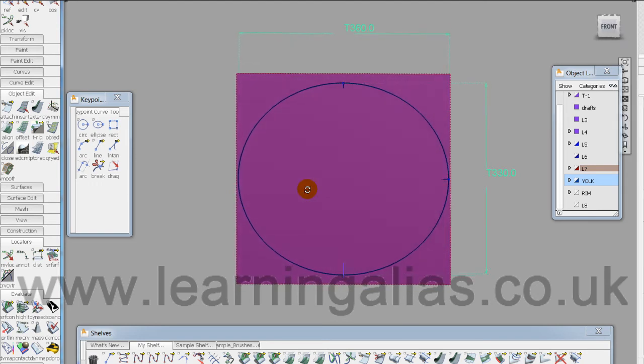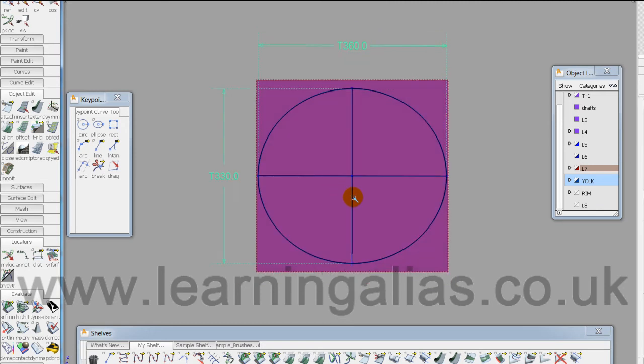It's okay for concept work, but if you want something better, you're going to have to find a different way of doing it. The way I set this up is, going to F7, I build this primitive surface slightly bigger than I need. Then, let's put the grid back on again, I bring my first curve in here and scale the curve to give me a major axis of 360 and a minor axis of 330. So that's the preparation for building the steering wheel.